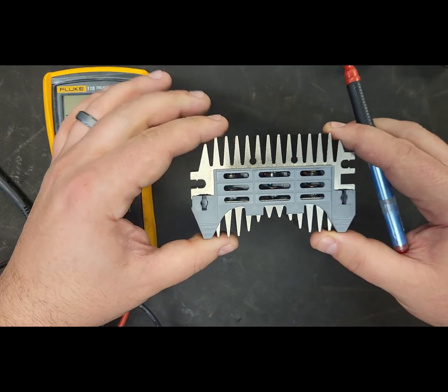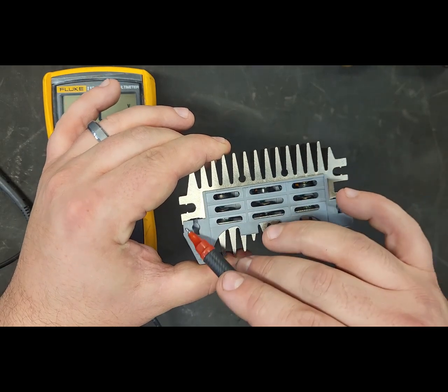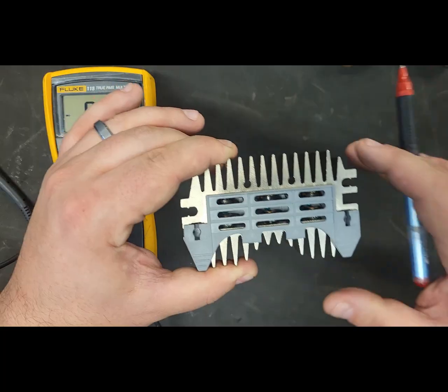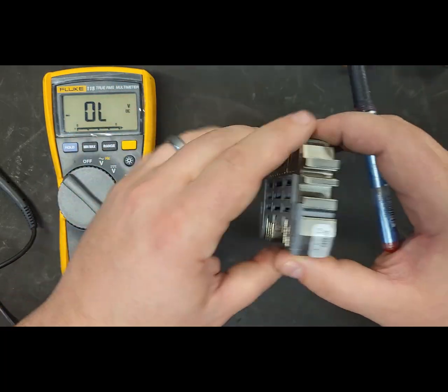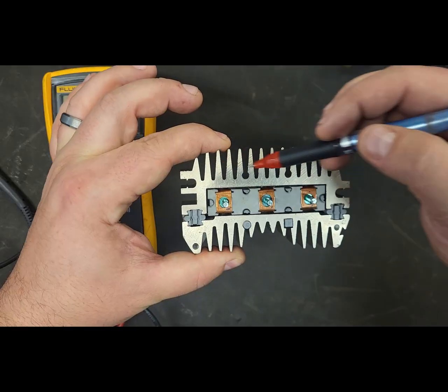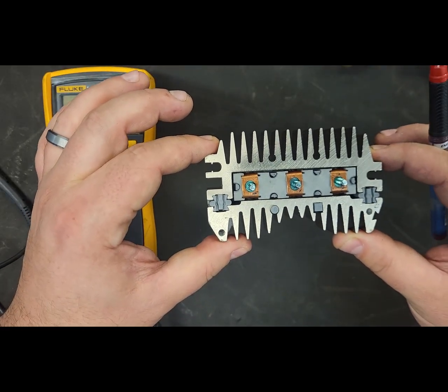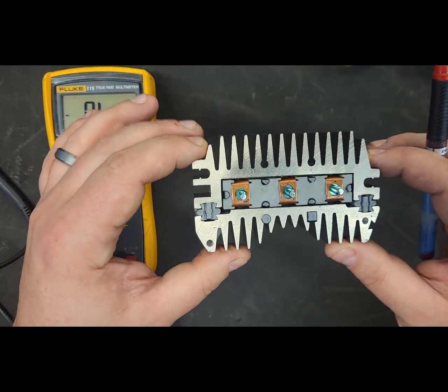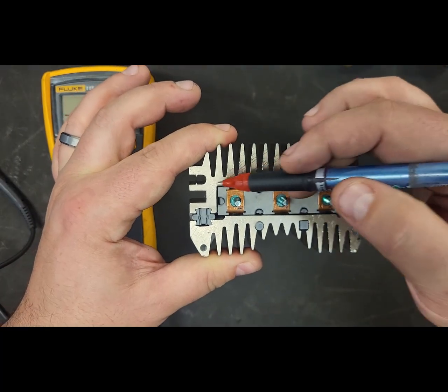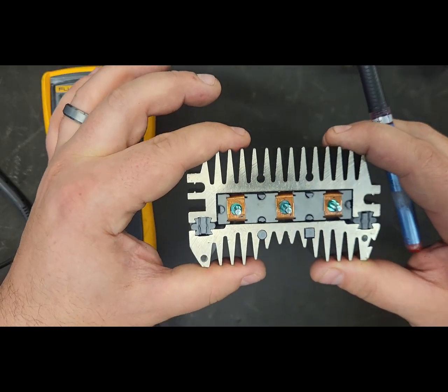You'll notice that 2 of those are utilizing this big plastic isolating shield from our case ground inside of our alternator. We're going to find which heatsink, well, what the heck's a heatsink? The heatsinks are these big aluminum chunks of metal that are going to help to dissipate the heat that my diodes are going to release. They release a lot of high heat. These are high heat generating components, so they're attached to my heatsinks. These aluminum fins will pull that heat out and try and dissipate it out to the air that's being pulled through that alternator.